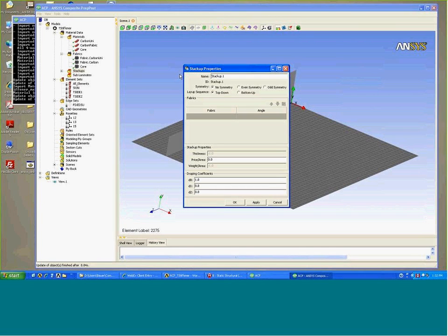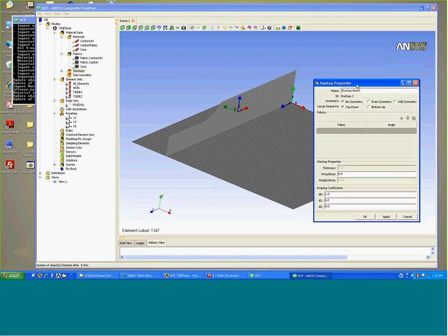In this example, I'm going to put in a stackup here called Stackup Book 1, and I'm going to generate essentially a pre-built 6-layer stackup that I can utilize for plies across the model in various regions. So this allows you to quickly apply this to different regions of your model.